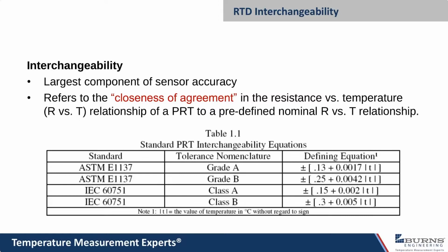Oh, in thermocouples, there's quite a variety. Like this is going to be a type J. One of the conductors is iron, and in the type T, one of them is copper. Type K, I think it's International Nickel Company, has a couple of trade names like Chromel and Alumel, which I don't know the exact chemical analysis of either one of those, but they do use different metals, and they'll all behave differently.